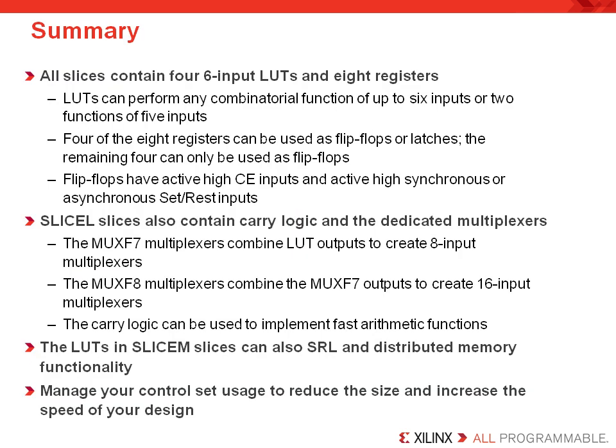In summary, all slices contain 4 6-input LUTs and 8 registers. The LUTs can perform any combinatorial function of up to 6 inputs or be implemented as 2 functions of 5 inputs. 4 of the 8 registers can be used as flip-flops or latches. The remaining 4 can only be used as flip-flops. Flip-flops have active high clock enable inputs and active high synchronous or asynchronous set-reset inputs.